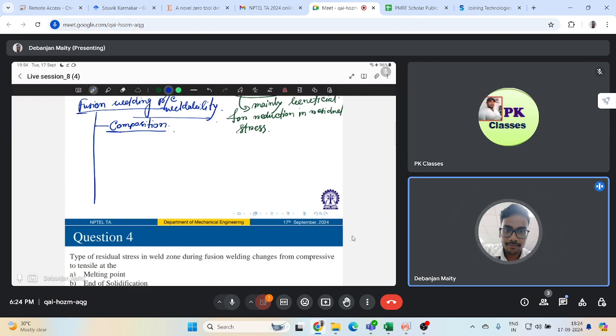So how will my composition affect my weldability? Metals can always have some unfavorable elements, whenever you have some alloying powder, or let's say you're doing additive manufacturing of some alloy powders. It can have unfavorable elements like lead, sulfur, phosphorus, some low melting temperature constituents that can also increase your cracking tendency. Weldability defines whether your welded structure has greater or less affinity to cracking, right?